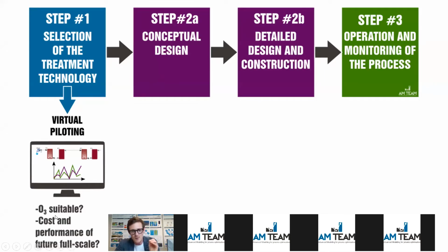So the questions you have are, is ozone suitable? If so, what is the bromate potential? What is the cost and performance of this future full-scale installation? Typically, people put pilots on site. They run it for a couple of months to over years, and then they collect a lot of data to see what the performance is.